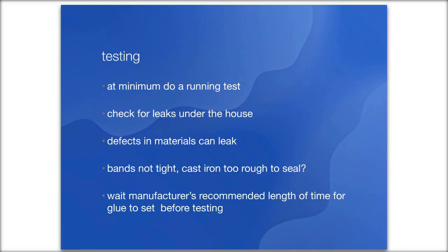But if you do a running test, have the water from the fixture that you are capturing the Greywater from running through the whole system. It's really important to check for leaks underneath the house, because obviously you don't want to be responsible for something that could create problems in the future. And even though you may absolutely trust your own workmanship, it's important to know that materials can have defects. What you're checking as much as your own work is the materials that you've used, because sometimes they will have holes in them or some other problem that you would never imagine.